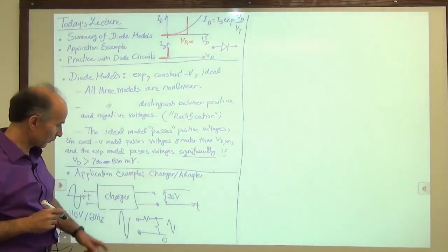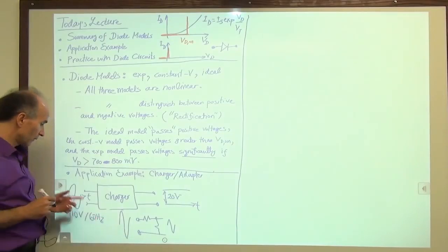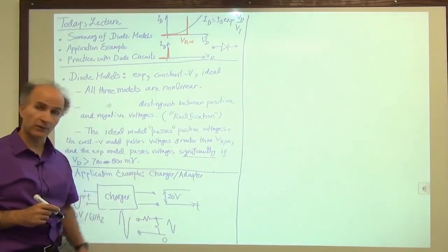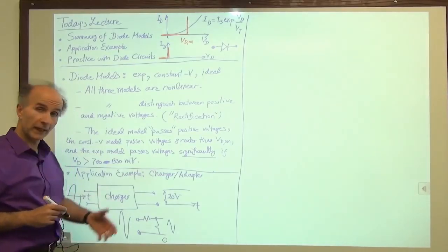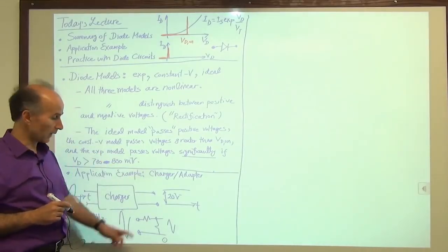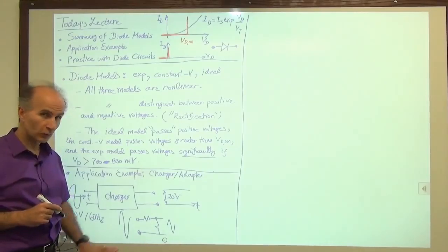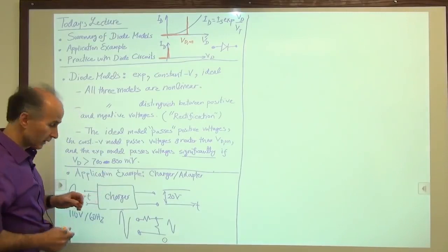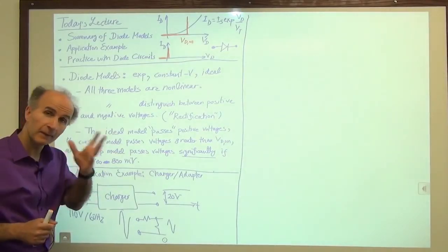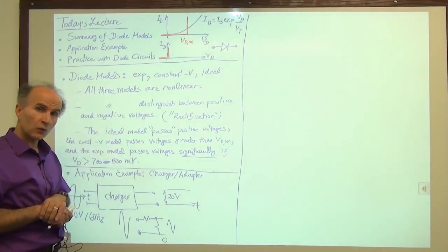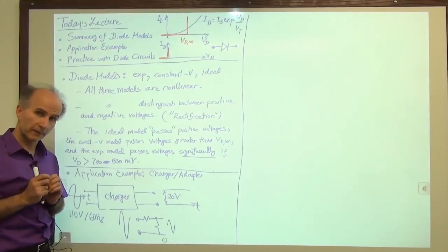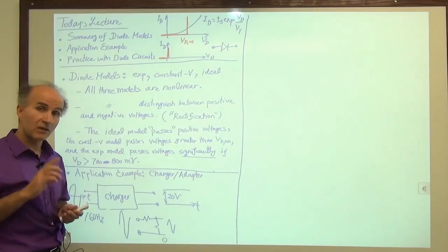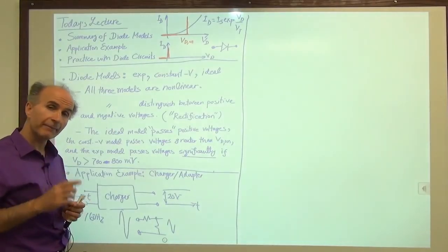Well, the problem is that when you apply such a large voltage to this resistive divider, we burn a lot of power in these resistors. So this charger will heat up dramatically, and that's a waste of energy. So we don't want to do that. We want to look for something that is more efficient in reducing the swing without dissipating energy. So we should look for some other element besides the resistor. Some element that at least nominally does not have power dissipation.